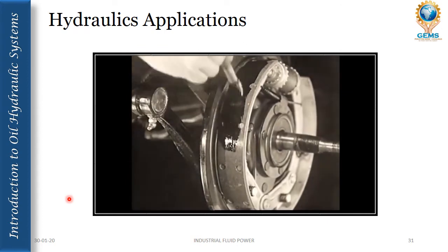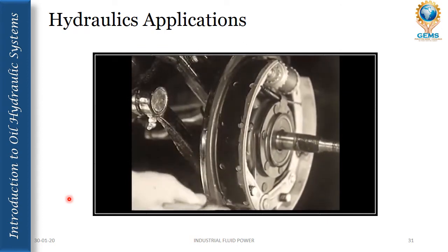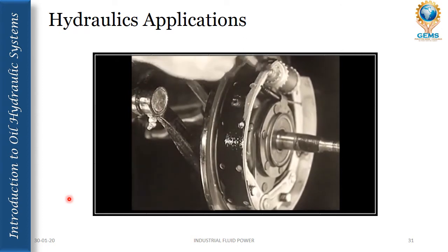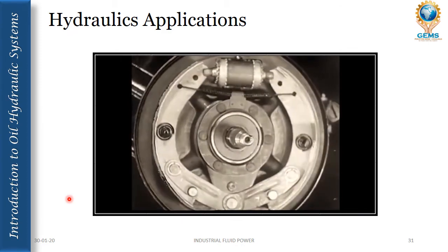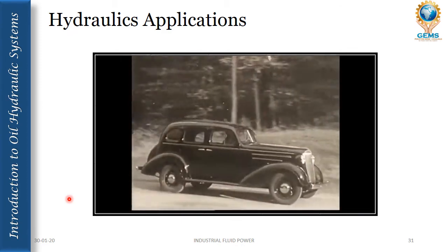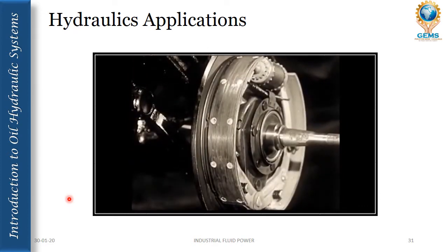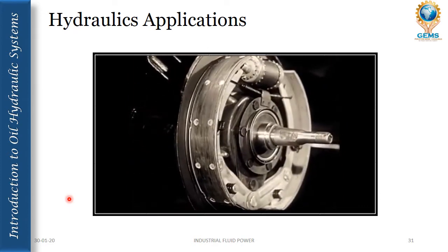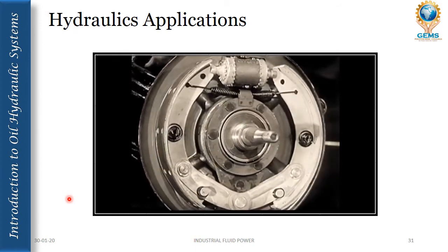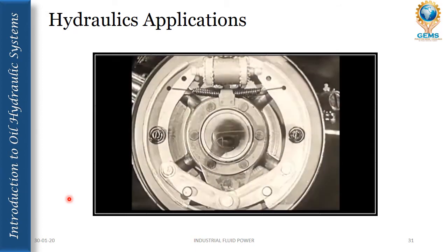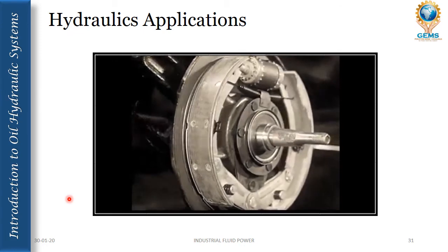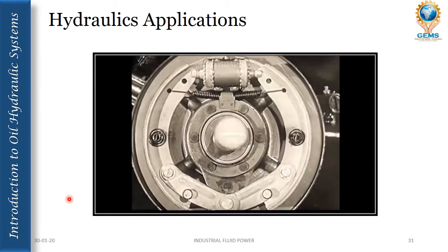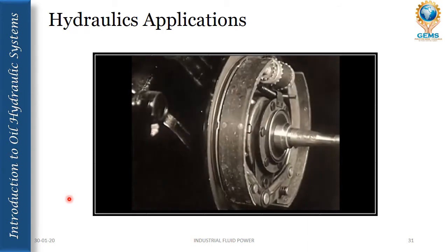These are the brake shoes of a new car. Let's paint this pair black and examine the wear they take. Note the even grip on the shoes in the first 20 miles. Perfect contact at 5,000 miles. And after 20,000 miles, uniform wear and still good for many more.